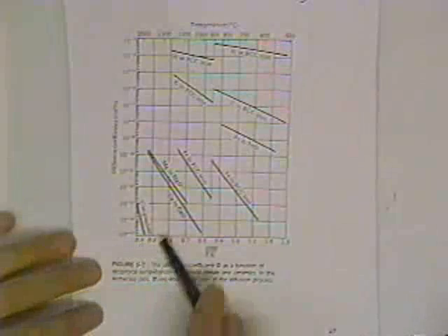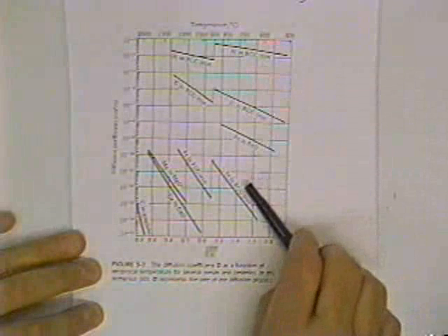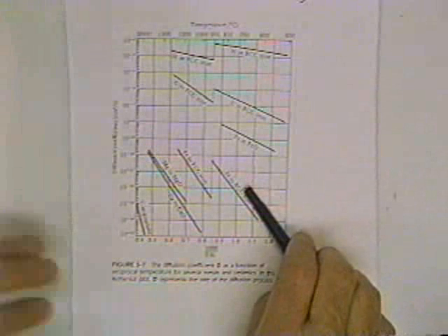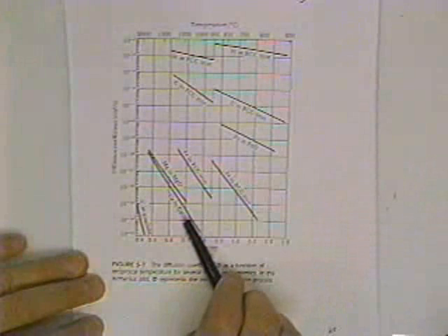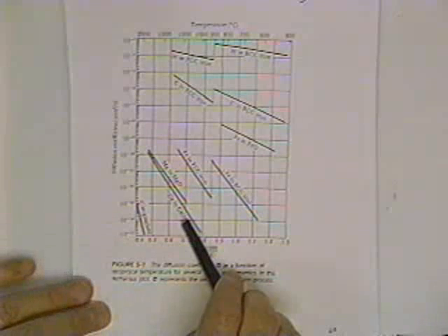So we can say something about the relative magnitudes of the activation energies because of what we know about their diffusion. Interstitial diffusion, relatively easy. Substitutional or vacancy diffusion, a bit more difficult because you have to have vacancies. And in ionic covalently bonded materials, we're going to have to break bonds, and in ionic be concerned about charge, which makes diffusion more difficult.